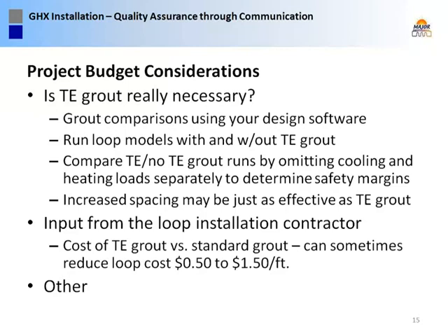Another thing that I'll do is I found that I can reduce the need for thermally enhanced grout by increasing spacing. A lot of guys just say 20-foot spacing and we'll call it good. I found by going to 25 and 30-foot spacing, a lot of times GLD will project that we don't have that much of an issue or much difference on maximum entering water temperature. So it all depends on the conductivity and how quickly your load spikes. So that's really important to have a good 8760 annual hourly load to do your design work with.